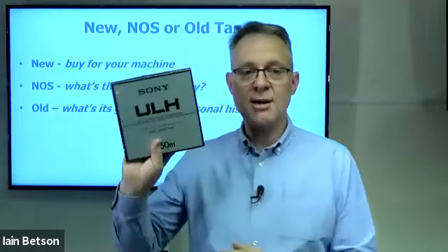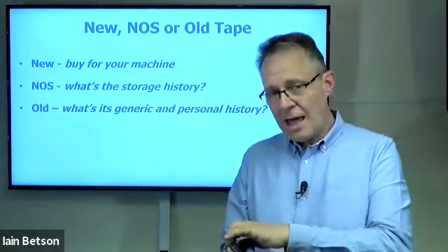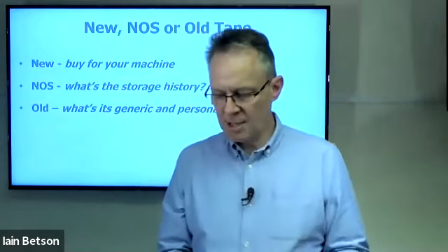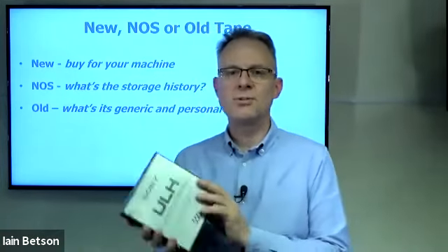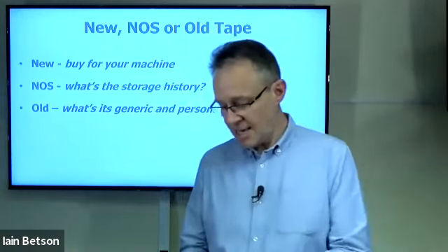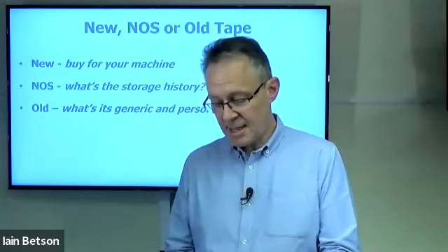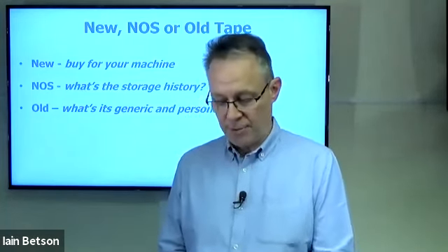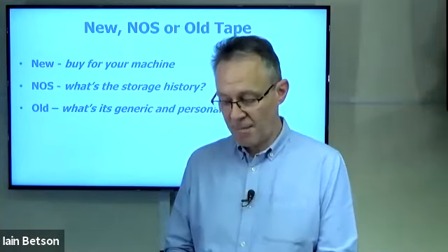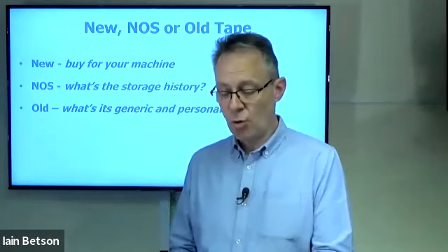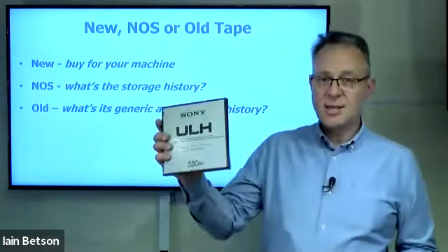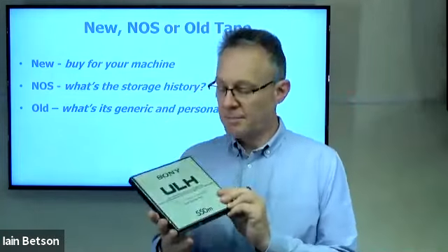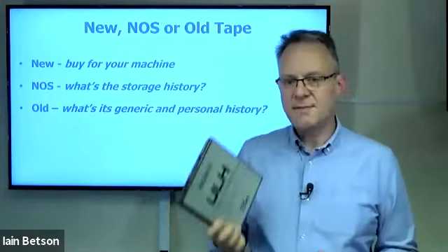There's another one here I've got, Sony ULH tape. I have a lot of these tapes because people sometimes ask me to line machines up for the particular tapes they're using. They record a lot of material perhaps on their Sony ULH tape. I did some research on the Reel to Reel Warehouse site, and it says, and I've made a note of it, it's a good performance level, high output, and it's got quite a high bias. You should over bias it, but it says playback only, do not record, sticky shed, must be baked before use. So that's the Sony ULH tapes. If you've got some of that, perhaps it's starting to not be in the best of health.